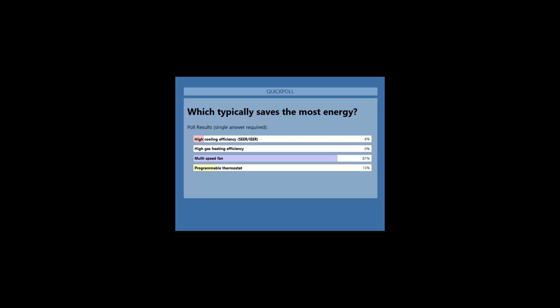Then when you get to the big units, 15, 20, 30, 50 tons, they'll typically have 2, 3, 4 compressors available for them instead of multi-speed compressors. Another thing we do is we might take 2 compressors and get you 3 stages out of it. These are just on-off compressors. They're just 1 stage each.